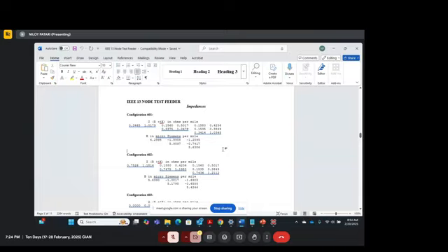Now line charging capacitance is pretty small. It's very small, so you can pretty much neglect this part when you model distribution systems, because this line charging capacitance is very important for transmission systems. The reason is that transmission systems are long and have very high voltage, right?